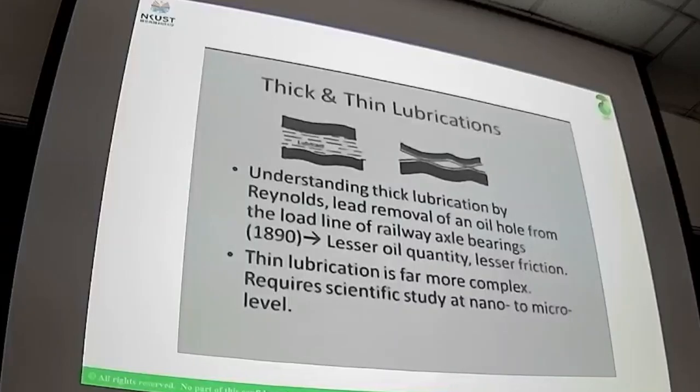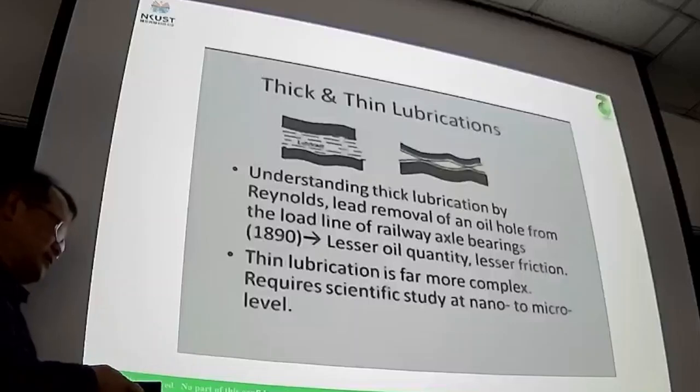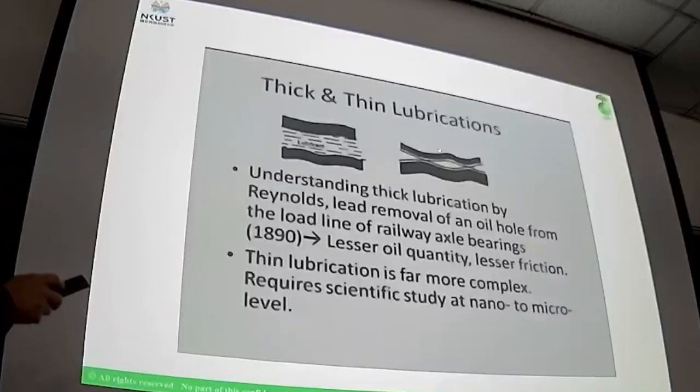One point you can understand by watching these two drawings: for the thick lubrication the two surfaces are separate, so there is no physical contact between them. But for thin lubrication, some asperities or high points are still contacting each other. Okay.